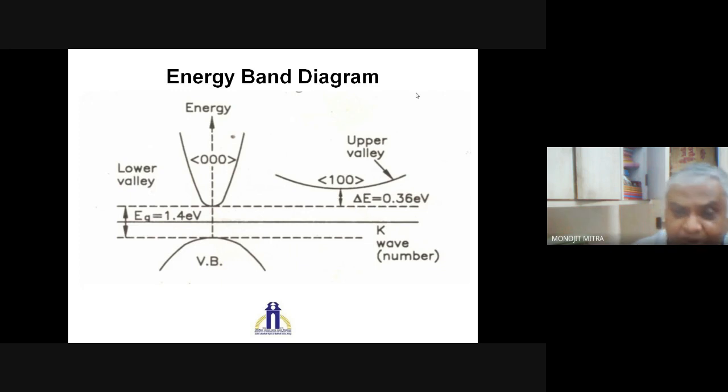less than 0.36. And I told you why it is required, because if it is not so, that means if KT0 is more than that, then at room temperature, the electron transfer effect will start. I hope that you can understand. No need for any external voltage or field. From energy, the electron will gain from room temperature, and with that energy, the electron transfer effect will start. So that's why one of the necessary conditions is that KT0, that is energy gained by the electron at room temperature, must be less than the energy gap between the two conduction band values.